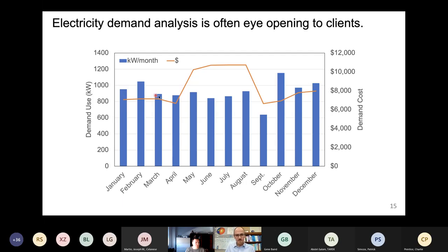demand charge was relatively constant over the 12-month cycle, you can see that they were charged much more during the summer months from May through August. And that's because the energy provider often does charge summer rates that are higher for demand. Summer is the time when everyone's running their air conditioners and there's a lot more load on the electricity grid, and so they're charging you more. If you're not paying attention to your demand charge, it can get out of hand.